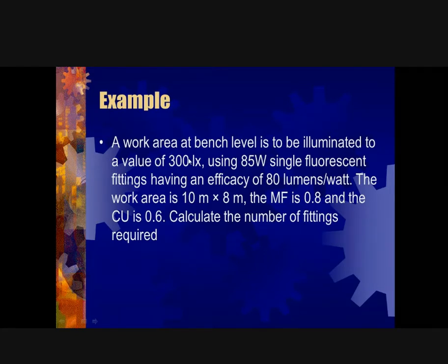So we already stated the lux because of the type of area, a workbench, so we want as much lux as possible. From established standards, we realize that for workbenches and work areas, 300 lux is actually sufficient. Using 85 watt single fluorescent fittings with an efficacy of 80 lumens per watt. The work area is 10 by 8 meters. The maintenance factor is 0.8 or 80%, and the coefficient of utilization is 0.6.